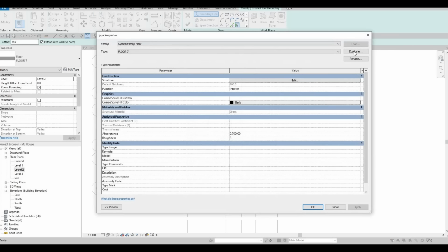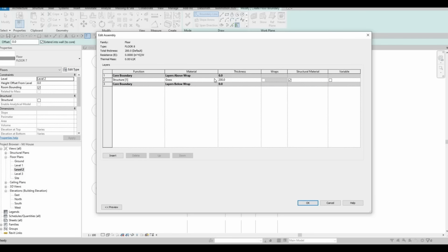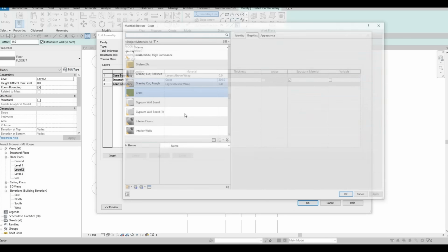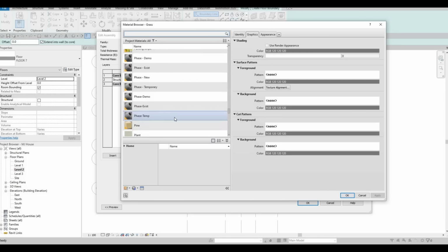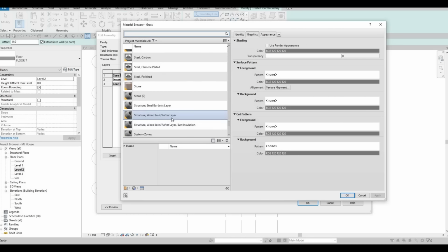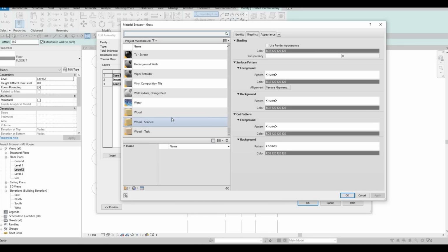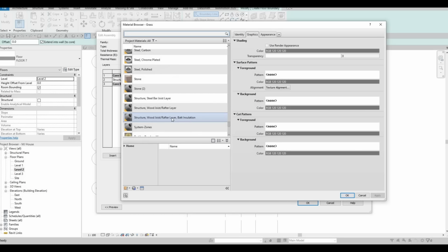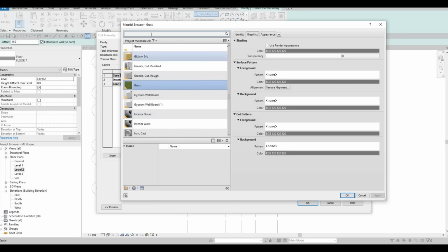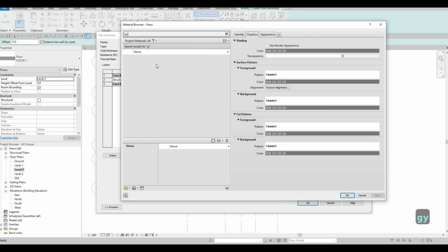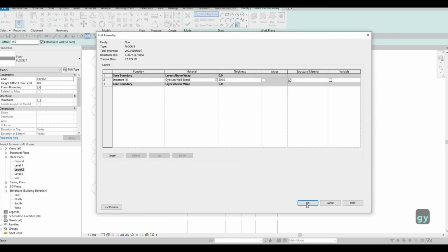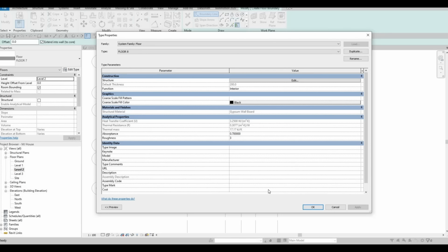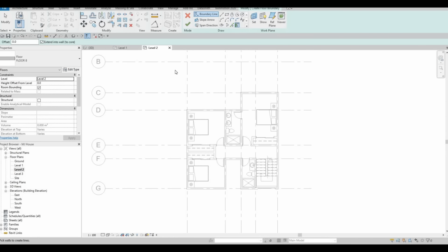This will be floor number 8. Maintain the 200 thickness, and then we're going to change it to a wood material. But because the floor and the ceiling will be the same, what I'm gonna do is I'm gonna put it at gypsum wallboard, and then I'm going to place a paint material on top of it.